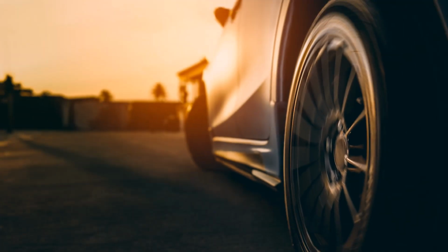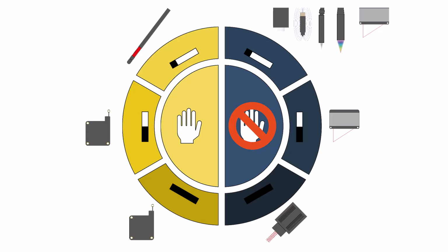In the second example, we want to measure the ground clearance of a race car. In that case, we definitely need a non-contact system, and since the suspension will have a travel in the mid-range, we can go with the laser triangulation sensor.